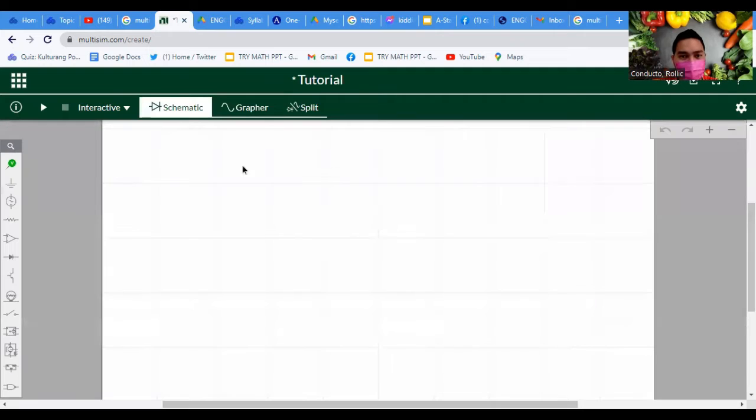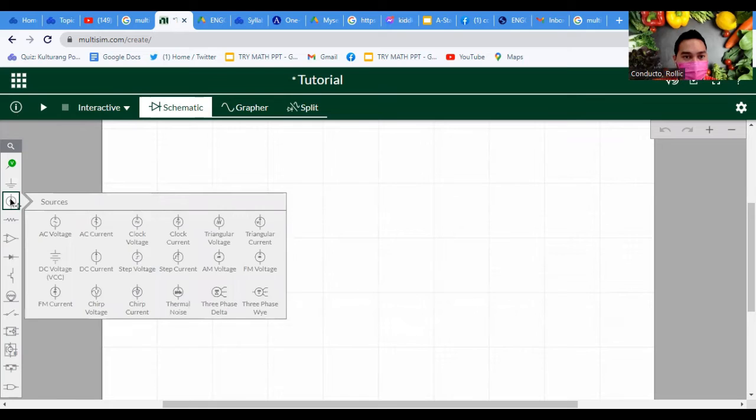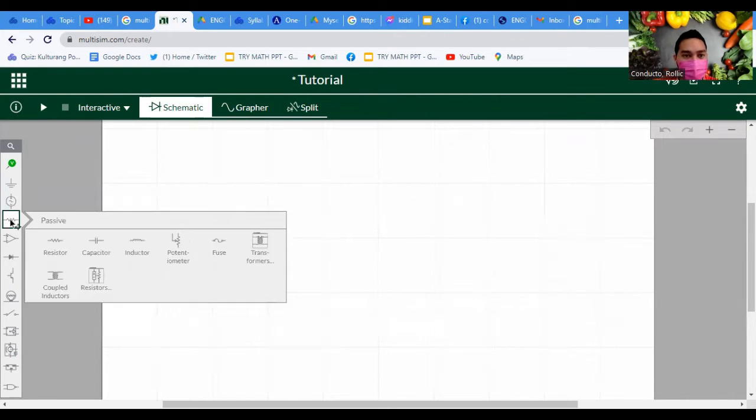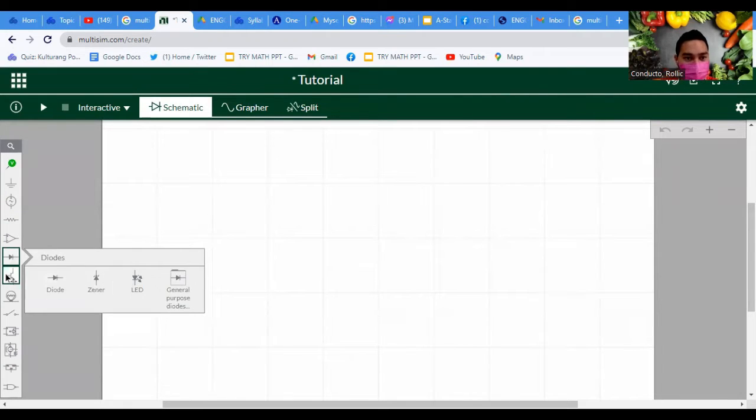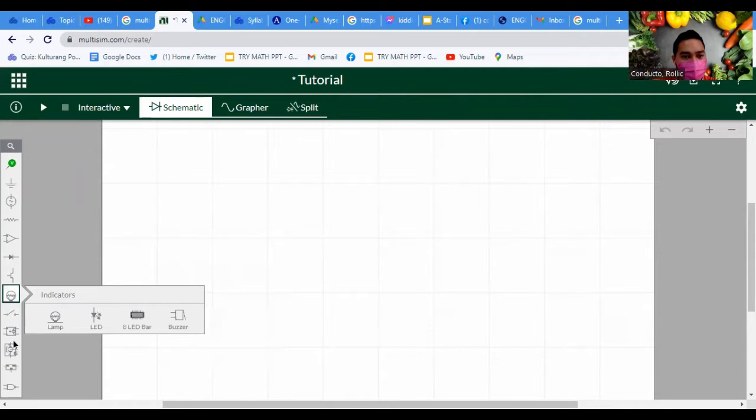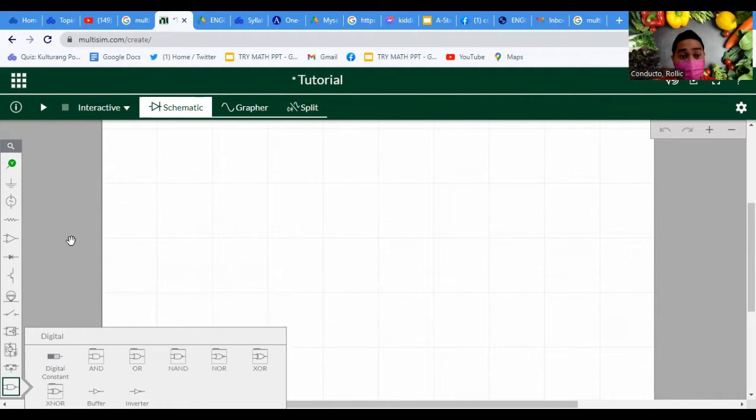Going to the schematic, in the last part, you can see all the tools and instrument symbols that we need in order to create our circuit. We have schematic connectors, the ground, the most usual one, junctions, connectors, the sources. We have a lot of sources in here. Just choose what you want. Then we have the resistors and other stuff. We also have transformers, op amps, our current lesson about diodes, and many other stuff. So for this tutorial, we'll be making a simple diode circuit.